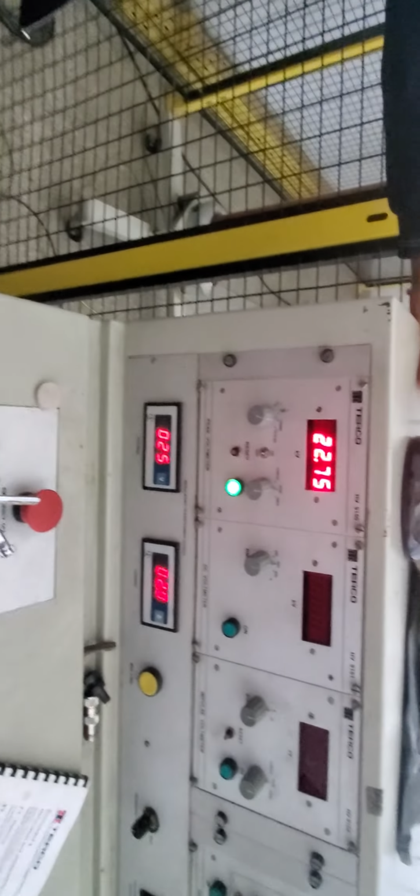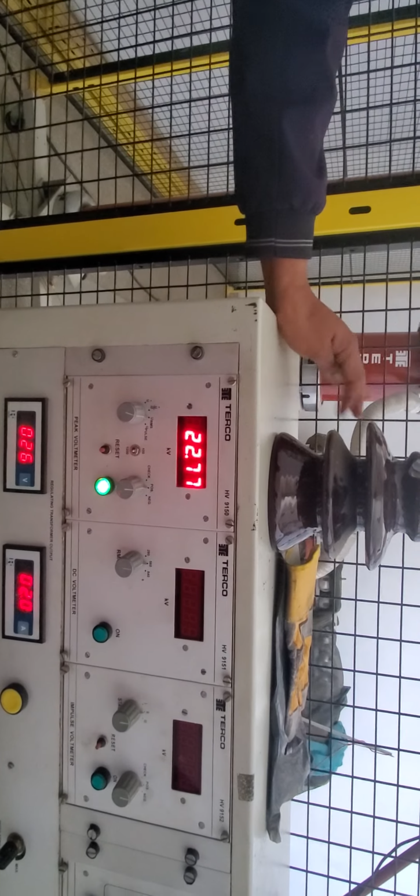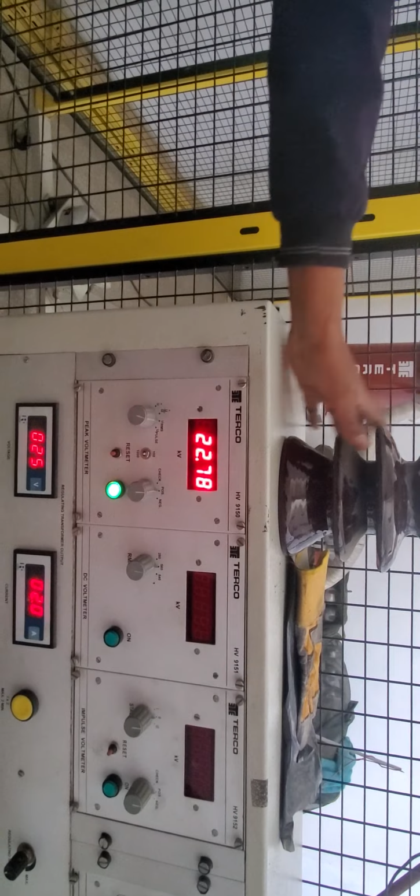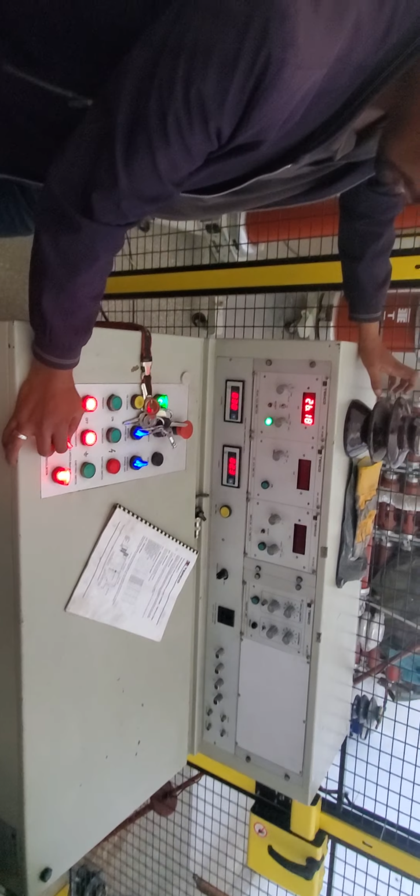So we are hearing the hissing sound. Whenever we go under any transmission line, we hear this hissing sound. Now if you increase the operating voltage, the hissing sound increases. That implies that the air around this conductor will what? Ionize. Corona means what? Ionization of air around the conductor.